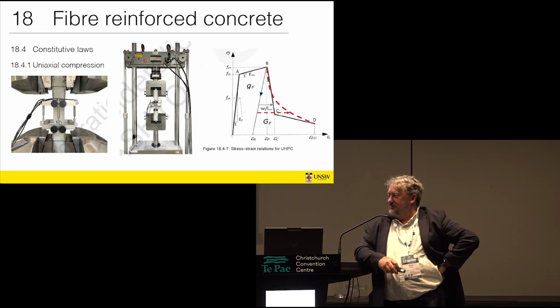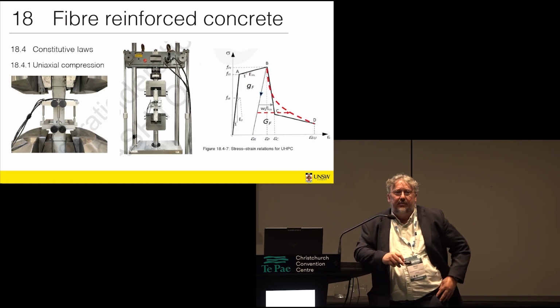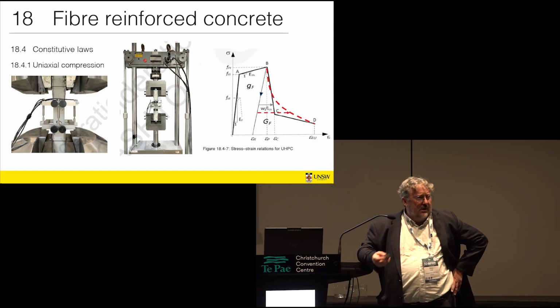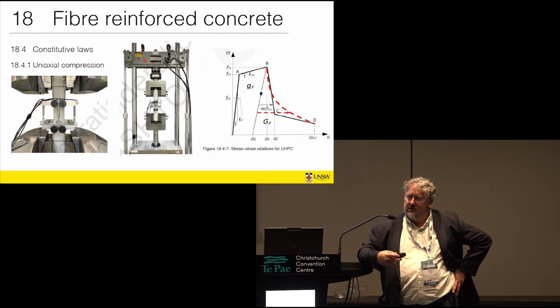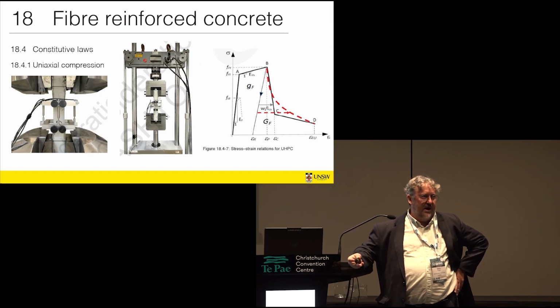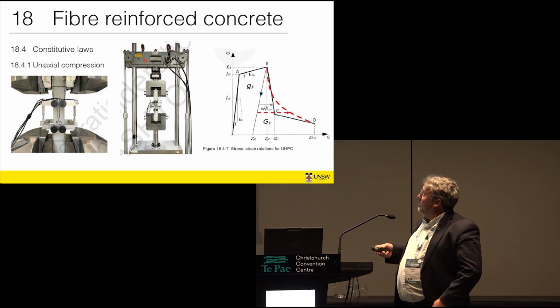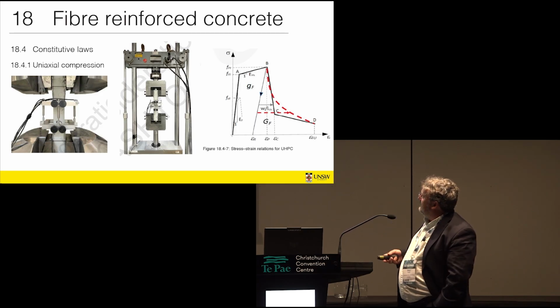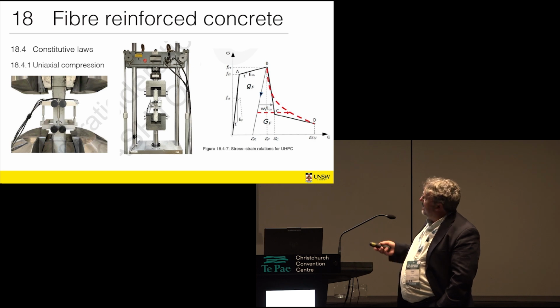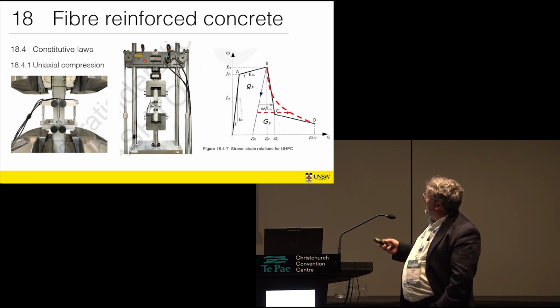All right, so just getting back to what the model code does cover. It puts in there a model for tension, and that's very important because we need the material properties characterised, and you can't do that with a flexural test. At least we haven't found a way of doing that yet. So you have to do a tension test. Good news is the Americans, ASTM, have a tension test which is being utilised.